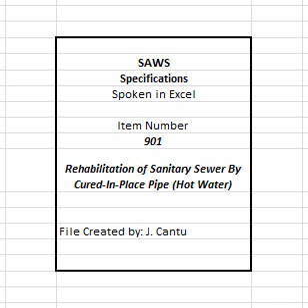D. Tube insertion. The wet-out tube shall be positioned in the pipeline using either inversion or a pull-in method. Under the inversion method, care shall be taken during the inversion process so as not to overstress the tube. If pulled into place, a power winch should be utilized and care should be exercised not to damage the tube as a result of pull-in friction. The tube should be pulled in or inverted through an existing manhole or approved access point and fully extended to the next designated manhole or termination point. The contractor shall install a gauge to monitor the pulling force of the pulled-in tube.